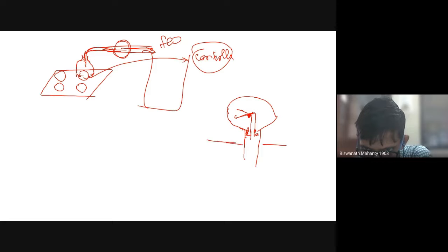This is closed, of course. Now pressure is built up, so air or gas is building up and it will push. The spring is there, so the increasing pressure will push the rod. As the rod pushes, it is connected with the meter dial, and of course the spring device is there, so it will change the dialing. So increasing pressure is mechanically transmitted through the spring. That is actually the pressure gauge.